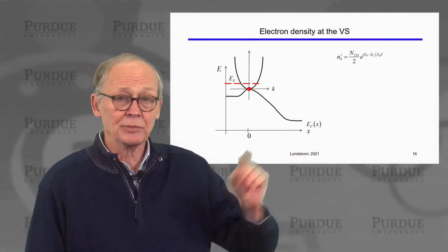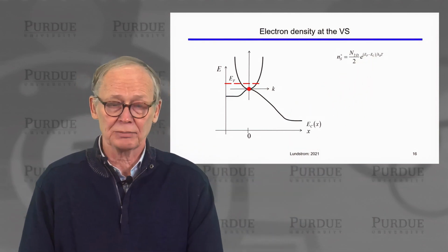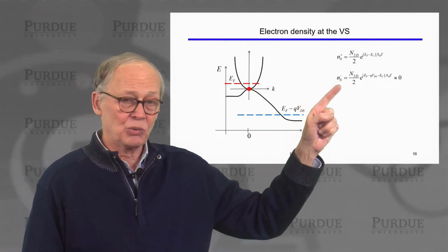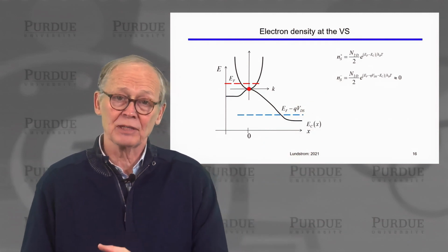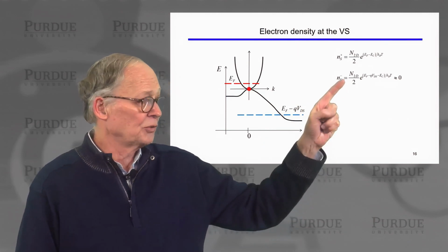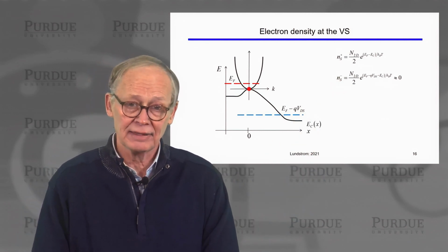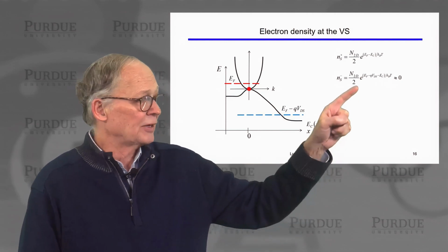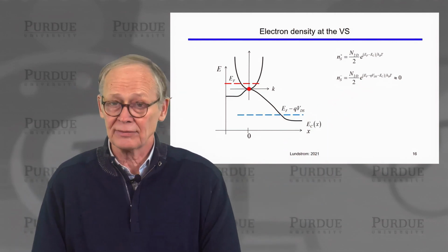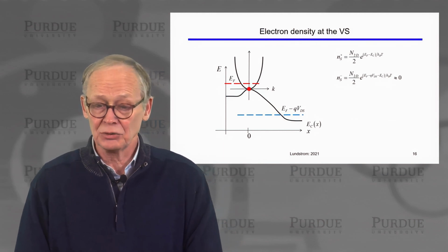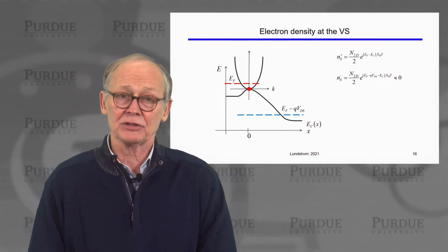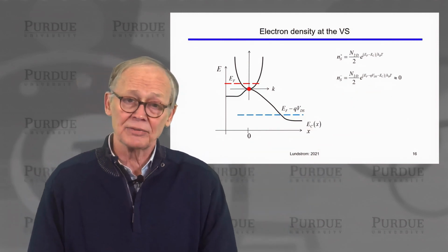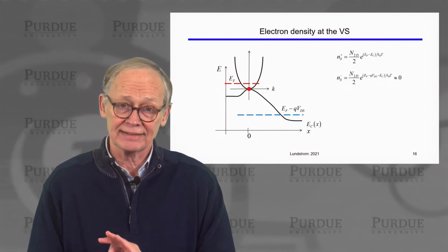And the Fermi level is the Fermi level from the source, because that's where the positive velocity electrons came from. Now, if I ask, what is the density of electrons per square centimeter with negative velocities? Well, also, only half of the states have negative velocities, so I divide the effective density of states by 2, and then I occupy those states according to the Fermi level of the drain, or contact 2, which is lower by an amount that's determined by VDS. Well, VDS is so large that the number of those negative velocity states is essentially 0.